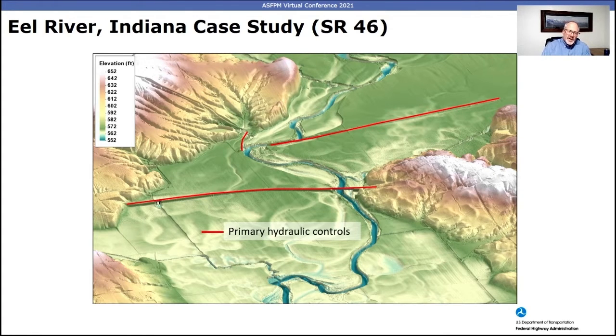With all 2D models that I'm familiar with, it's important to align element edges with these hydraulic features. Because if the tops or crests of these features don't align with element faces, then these features are not going to be represented correctly. Basically, if the features are located inside or through the middle of an element, it won't see the flow across that element or compute the flow correctly. So arcs, such as those shown in this image, are used as break lines in the mesh generator, or just in the process of generating the mesh.